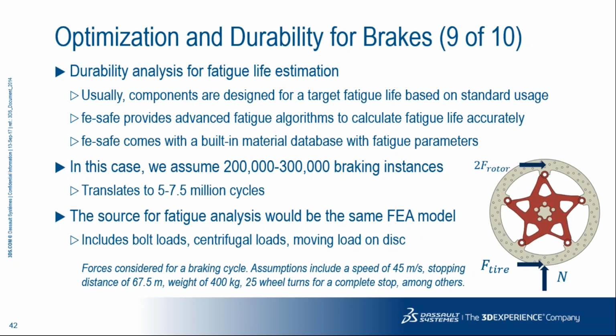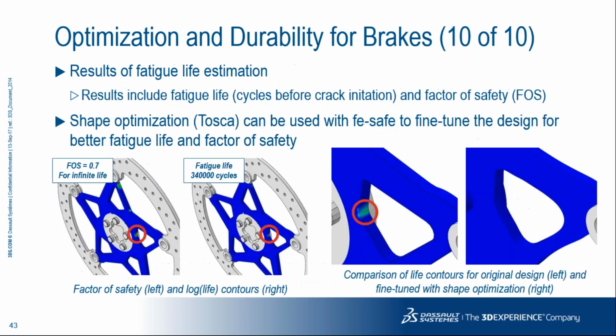In FEM, the brake pad moves from step to step and increment to simulate the load running around the disc, like centrifugal load and the bolt load. And finally, we use FE-SAFE to evaluate the durability of the brake rotor, since it has to withstand the simulated loads running around the disc, like centrifugal force, and also to predict the service loads. The life also depends on the usage, like how the tire and the brake have been used. FE-SAFE can also integrate with Isight for parametric optimization, as we discussed, and for design changes in case the durability is not as expected.